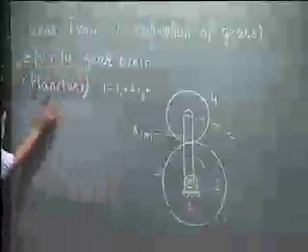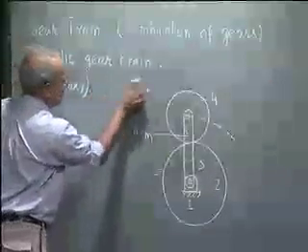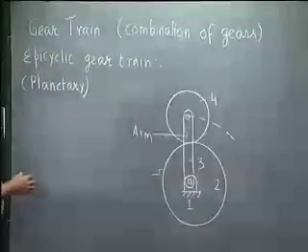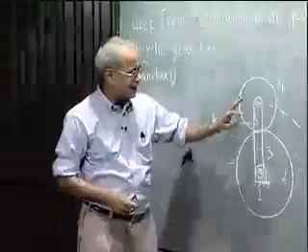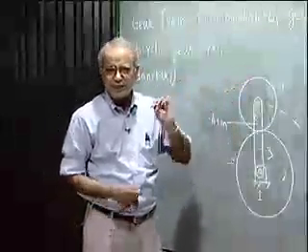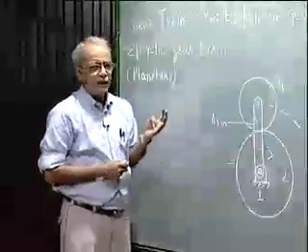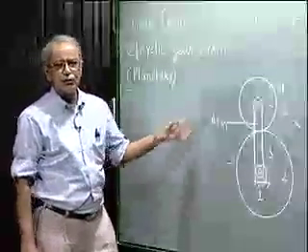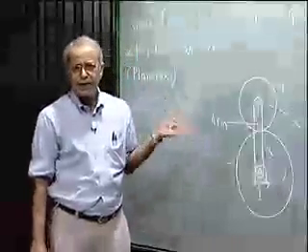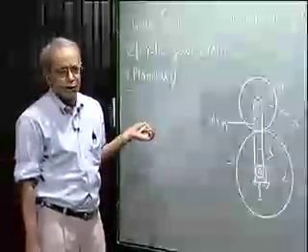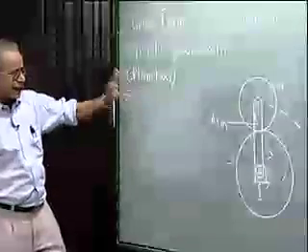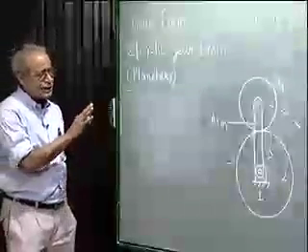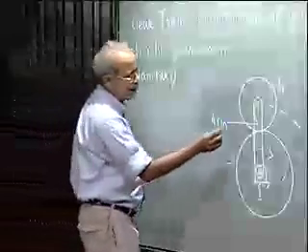Now how do I analyze such an epicyclic chain? Here, it will be very difficult to visualize the direction of rotation of various gears because this gear is not fixed in space. So let me try to develop a rather mechanical, analytical method to follow, without trying to visualize which way which gear is rotating, as it was possible in the case of simple or compound gear chains. So we analyze an epicyclic gear chain rather mechanically. For that, first of all, let us derive the basic principle of analysis of an epicyclic gear chain.